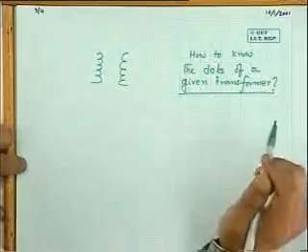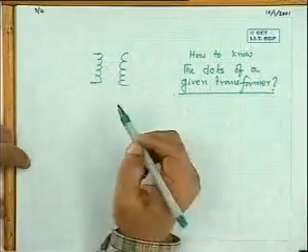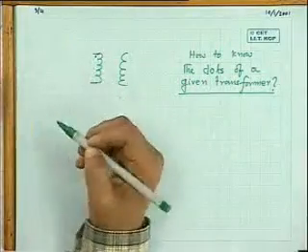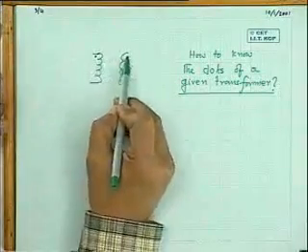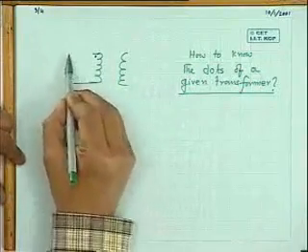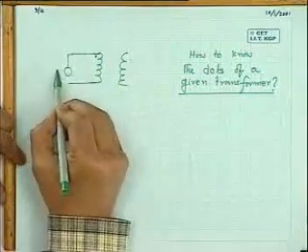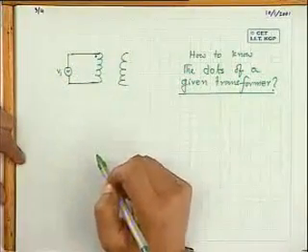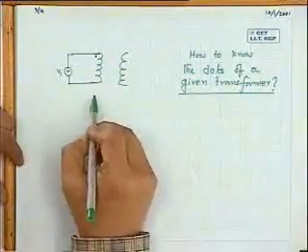For this, of course, you have to do some testing or some tricks. Suppose the transformer is given, I do not know where the dots are. Of course, you are free to choose one dot of a coil. That I can start with. Suppose this is positive at a point. Which one is positive, I want to know. What I will do is apply an AC voltage, say V1, the rated voltage of this winding.